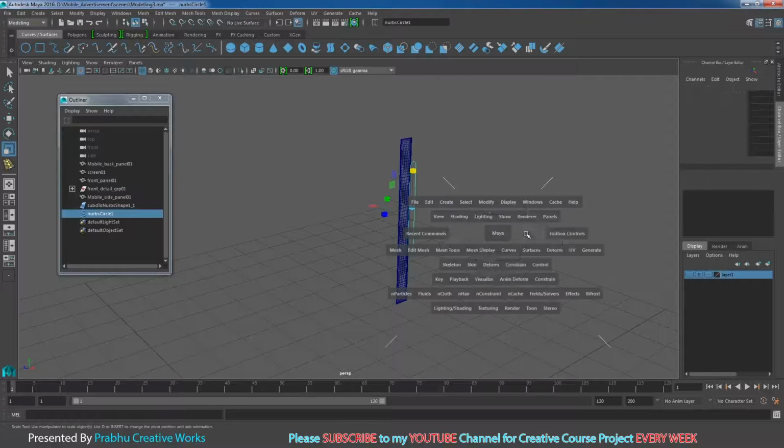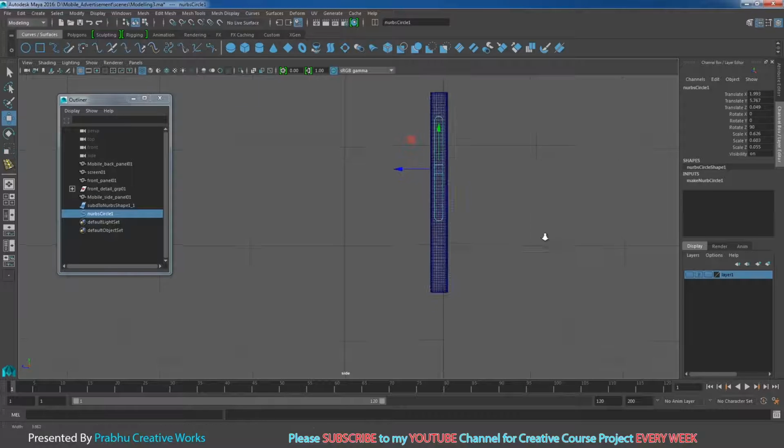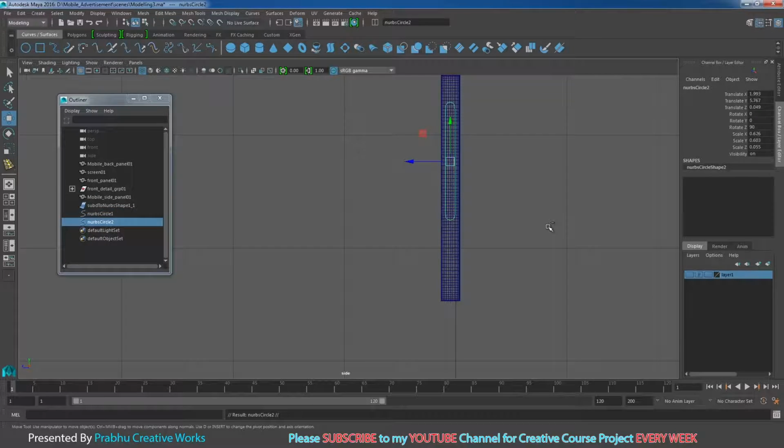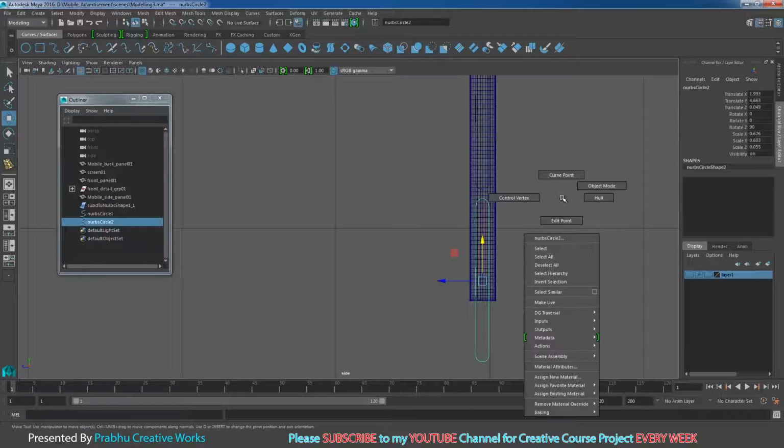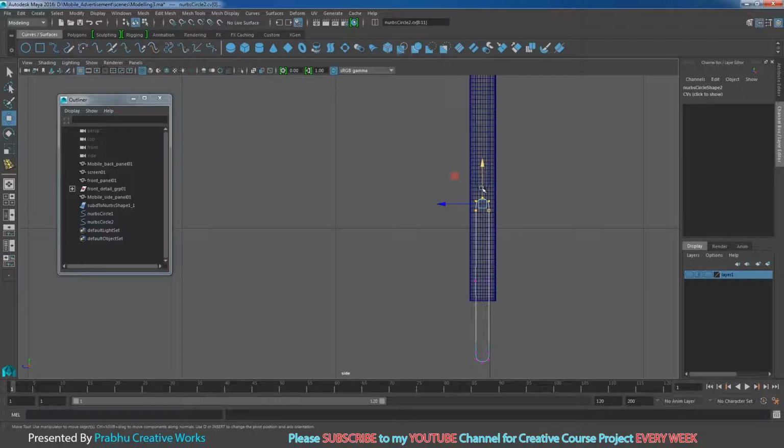Go to right view. Now press Ctrl D to duplicate. I want to move it, because here I need the lock button. Right click and choose control vertex. I will adjust this one in Y. I will select this one and move in Y.